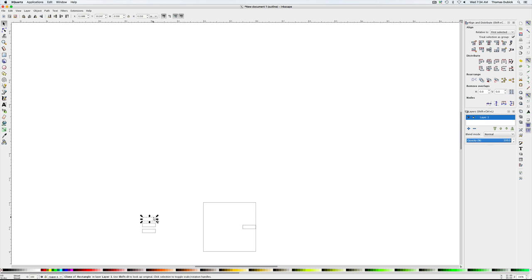So I'm going to take another one. Watch what I'm going to do. I'm going to put it first in the center of the, wait a minute, let's go back to page, jumped it, go to the center there, and then I'm going to go to the horizontal, then select first selected, click on the square, then use the shift key, click on just that little slot, go to align right edge of the object to left edge of the anchor, being the first thing I selected.